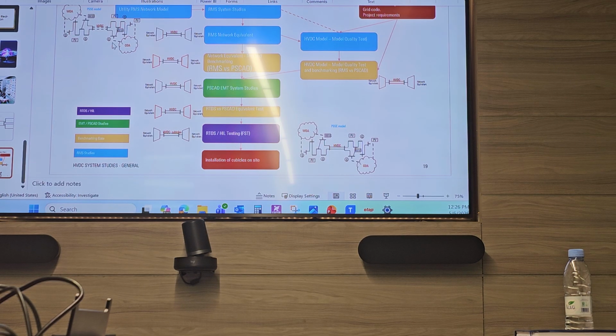Then we will do a fault at 100 milliseconds. The busbar voltage goes to 0, a three-phase fault in that case. Then the fault is cleared by protection. That means after 100 milliseconds, protection will disconnect this busbar with all neighboring ones. You simulate this case, and you see if the system will remain stable.